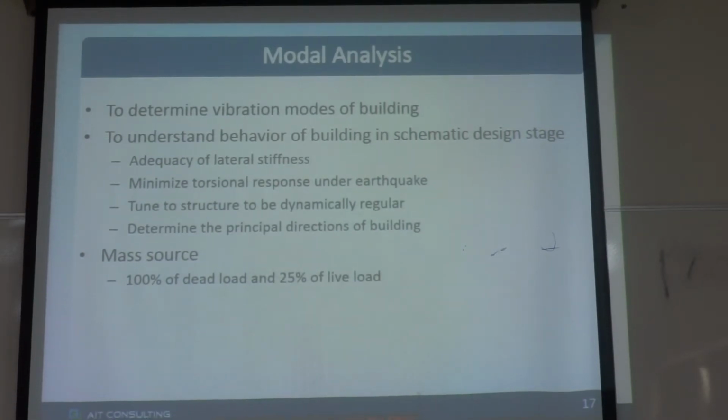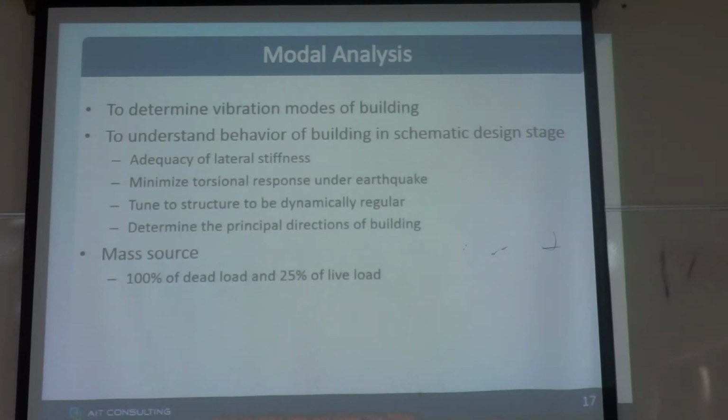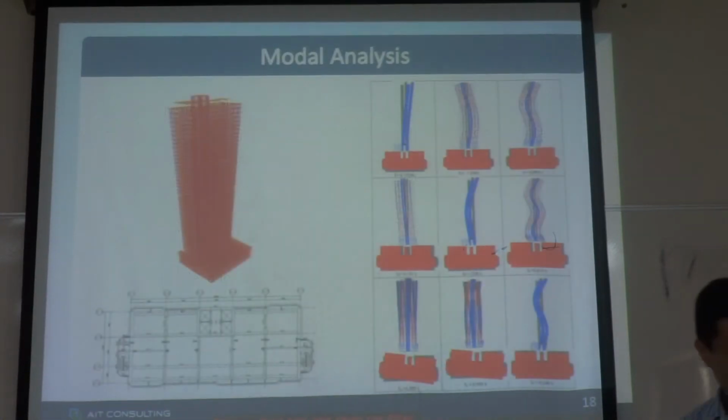But in reality, that live load will not all exist. Only 25% might exist. So we do not consider 100% for modal analysis and seismic analysis. Seismic loads are also calculated from the mass that you define.